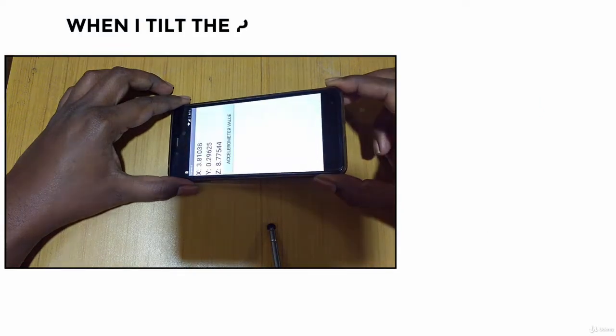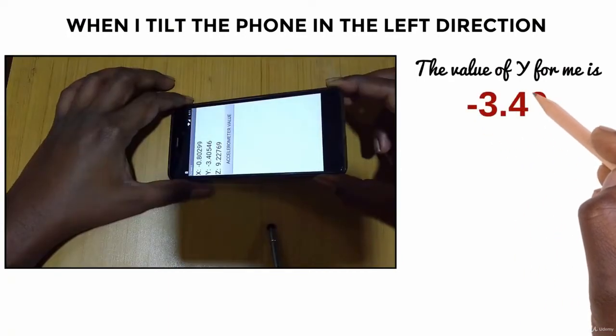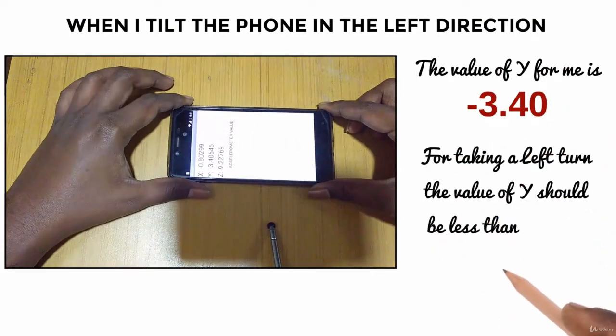If I tilt my phone left, then you can see there is a change in the Y-axis and the value of Y right now is minus 3.40. So if I want to move the robot left, the Y acceleration value should be less than minus 3, that is minus 4, minus 5.